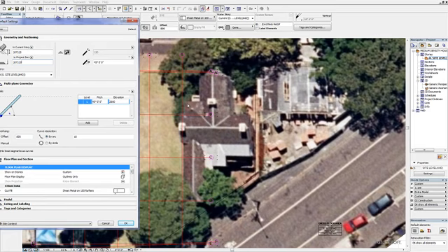So remember, before you went to site, I suggested that as much as possible you take photos of the sides of your buildings face on, or parallel to, so that you don't get any perspective distortions, or you get as little perspective distortion as possible, so that you can really understand what are the sizes of those buildings.